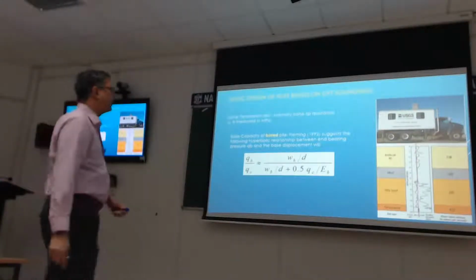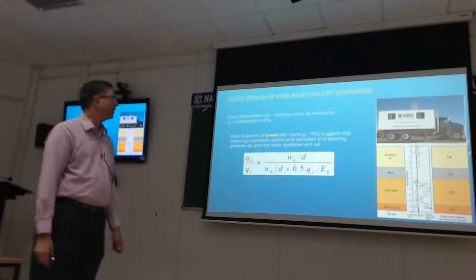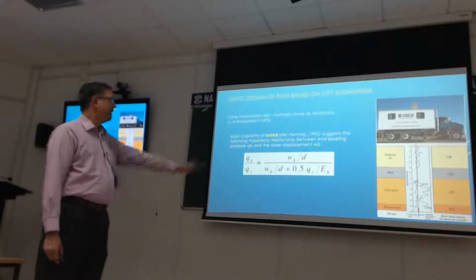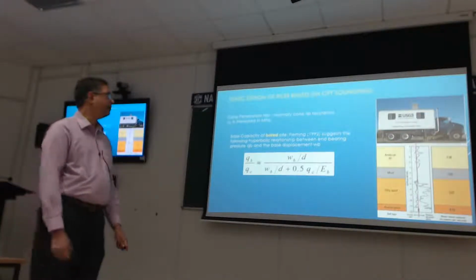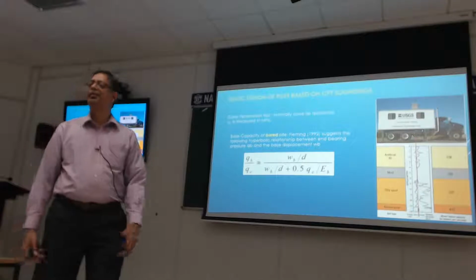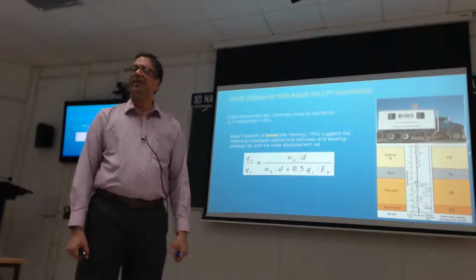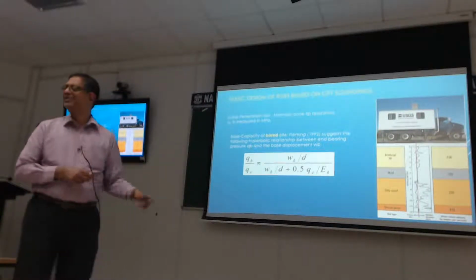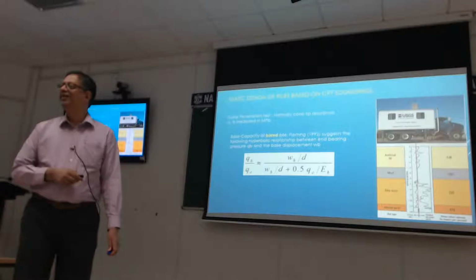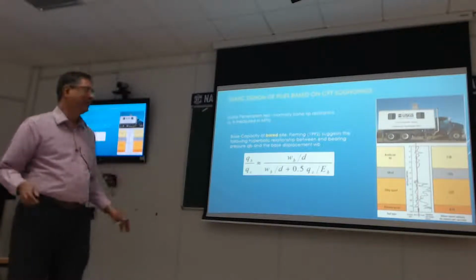So this is how it's typically done. So you got your truck, you drive to the site, and inside the truck you got your rod and your actuator. And the good thing about this is your truck is your reactant mass. So that's why they lift it. If you see the wheels of this thing, you may have seen a CPT truck. Maybe I'm being, no? Okay, then the picture makes sense. I'm sorry, I had to pitch it at some level.